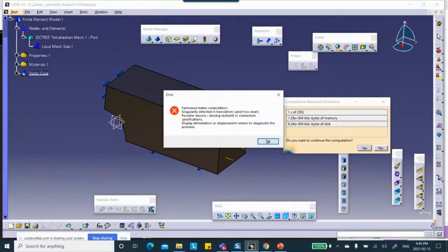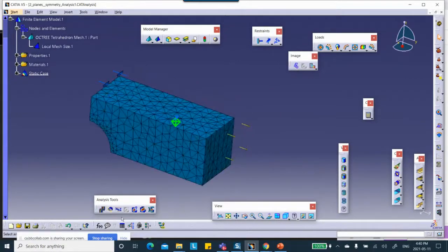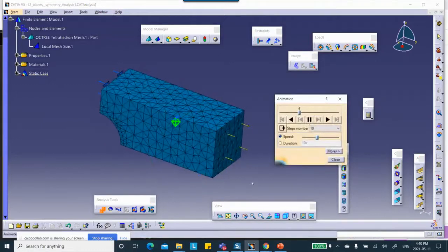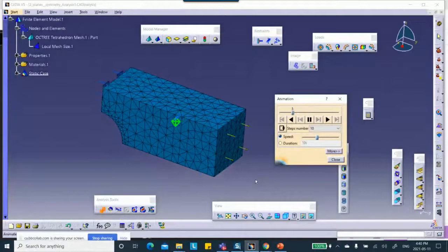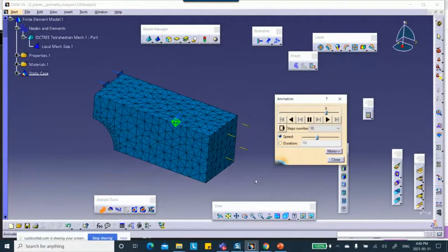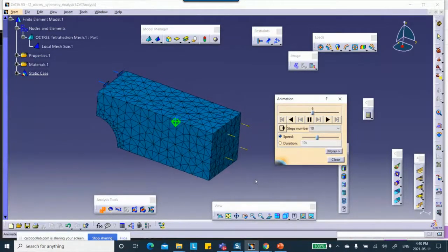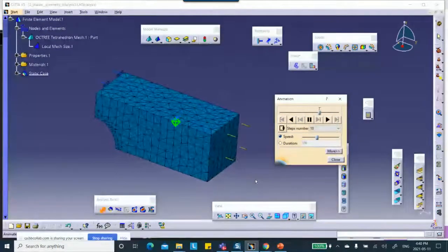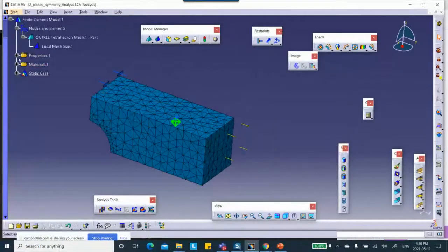And maybe if you plot the displacement, it will tell you something about what's wrong. Look, this is free to move as a rigid body. It's on roller on the side, it's on roller on the bottom, but nothing's stopping it from moving in the X direction. When you took 3 planes of symmetry, that surface slider prevented the movement in that direction. So we say, fine, we got to fix it.